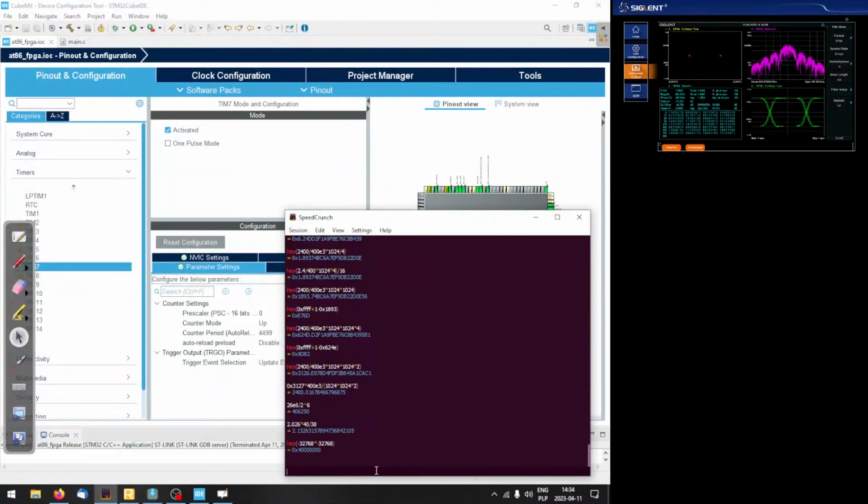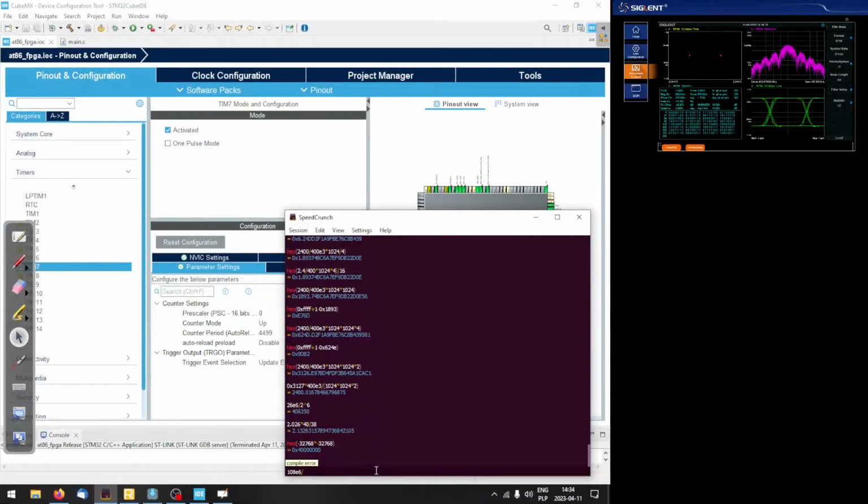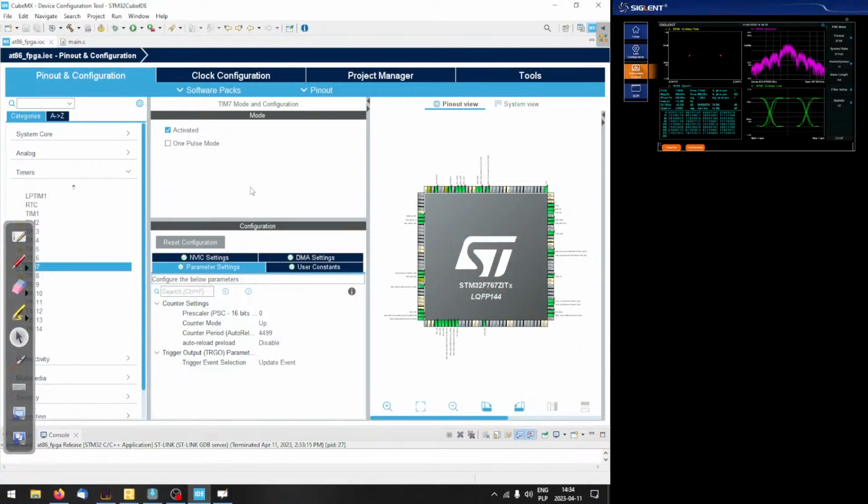Of course, -1, because it starts at 0. So if we know the clock value for that timer and divide we get 24K as the symbol rate. So that's the symbol rate, and that's the rate at which the SPI transactions happen between STM32 and the FPGA. So that's for the phase mod, for BPSK to be precise.